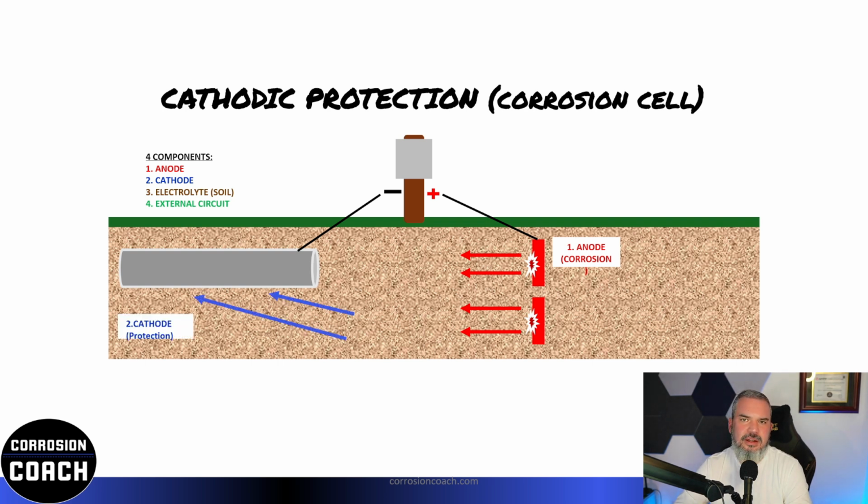We're going to collect it on our pipeline, and then it's going to be connected via a negative connection, and it's going to go back to that rectifier. So again, we're in the clockwise position today. This is what we call a cathodic protection system. So instead of the current discharging off of our pipe in this case, it's discharging off of the anodes.